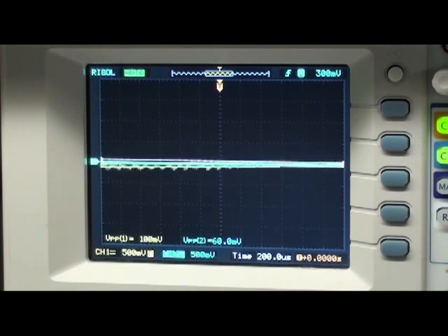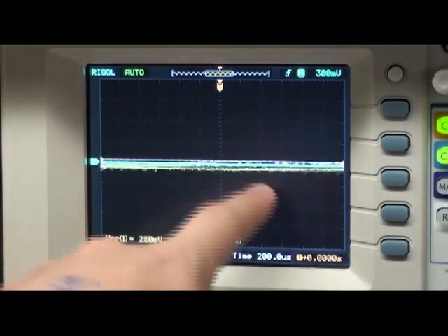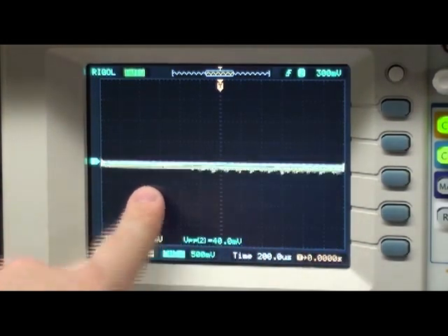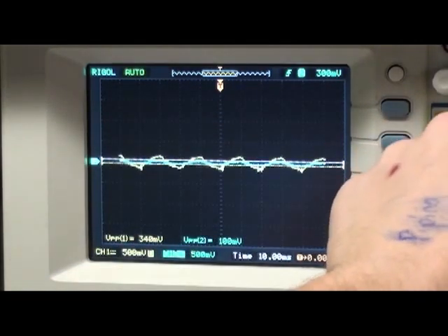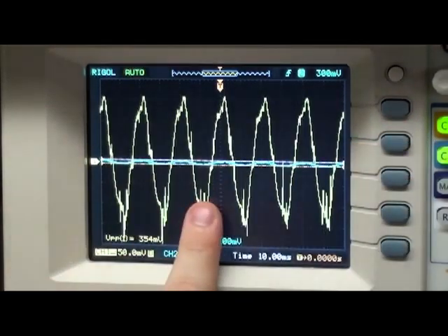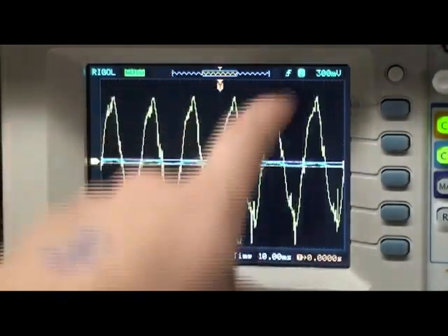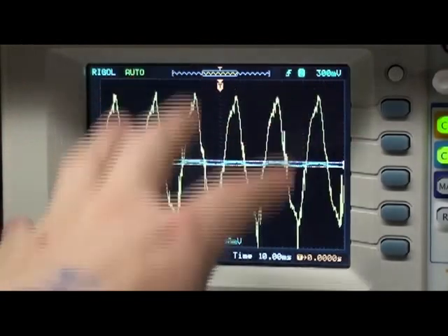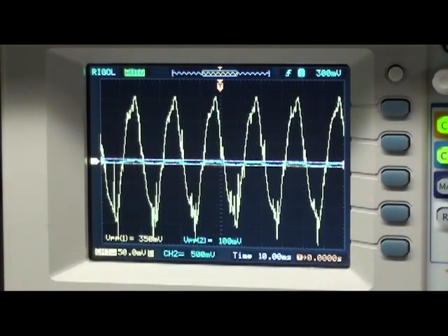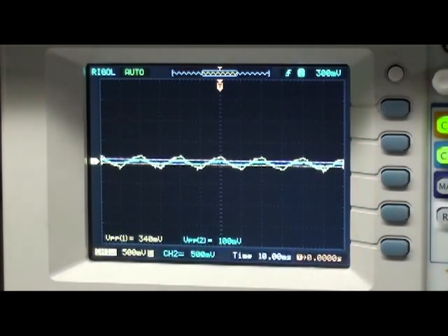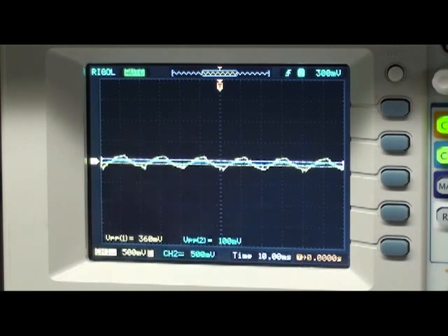Okay, so we're back on the oscilloscope, and as you can see it's doing some weird stuff with the noise. You'll actually find if you measure this, it will be a 50 Hertz sine wave. Let's see if I can see it. It's a pretty poor sine wave, but this is actually the 50 Hertz of all the power lines around here, just going through the air and going inside all my signals on the circuit, on the breadboard. So just keep in mind that noise is a real problem. But anyway, let's turn the function generator on and look at what our amplifier does.